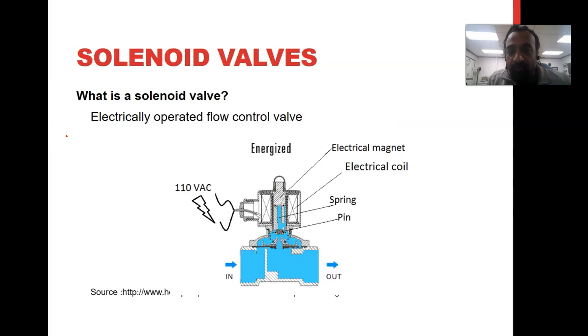Okay, let's move on. So again, solenoid. If you look at a solenoid valve, where are we going to see solenoid valves? There are plenty of those in your car. They are in the AC. They are in electrical valves and motors. What happens here is we have a solenoid over this area that gets activated and pulls this pin out. In this situation, polarity is very important, but here we're using AC current, so polarity is not the same. But if you're using DC current, that will be important because some of those are reversible as well.